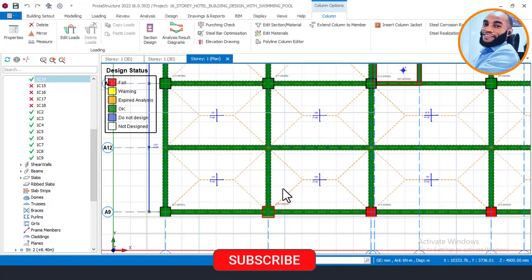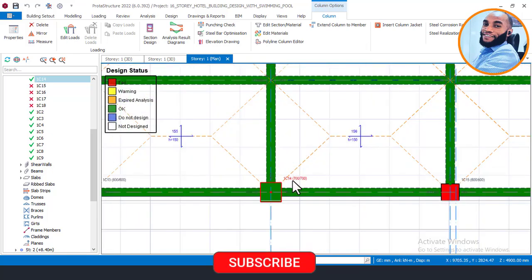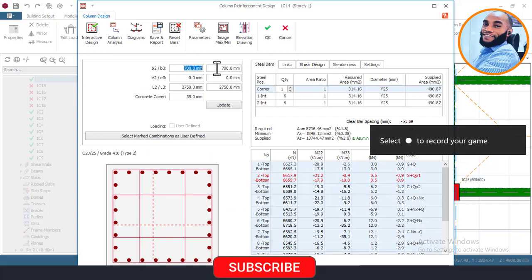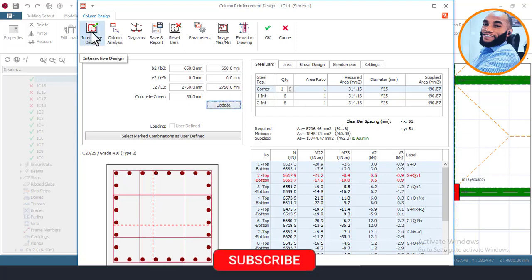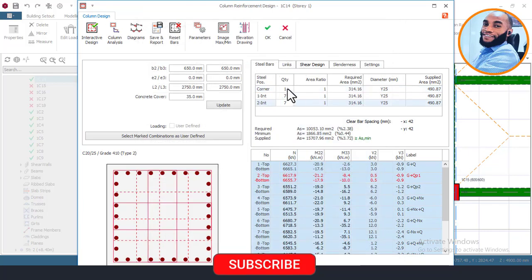Okay, but just to maintain, like I use the 650, just to maintain the same column size, so that I will not spend much time during your detailing. So always try to use few column sizes that will be grouped together, so that you don't have more column types. Okay, so I'll come down and click on here, reset first and then design. Okay, the number of bars will be given to me. That's okay. I can now come here and then click on okay here and then okay here.